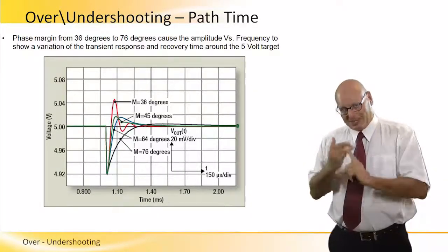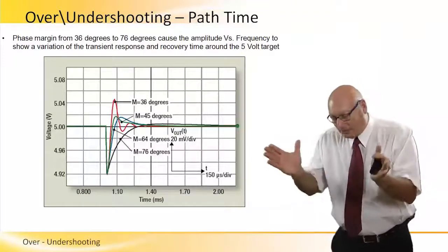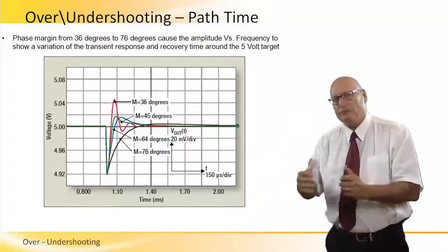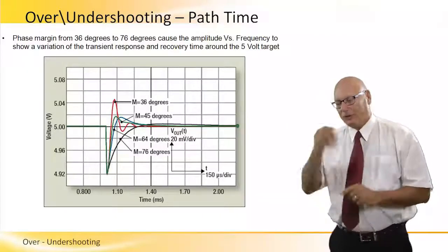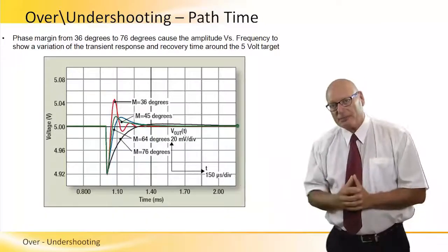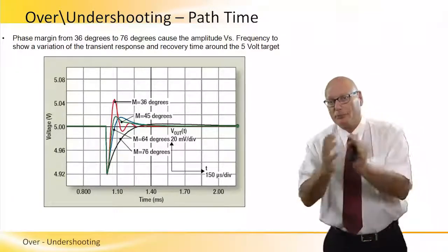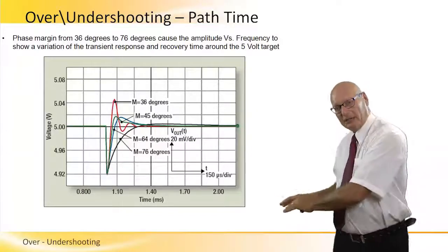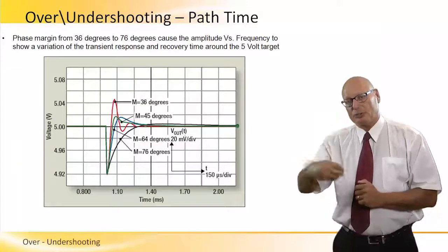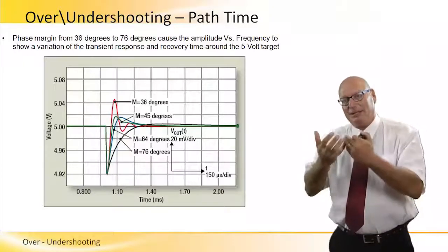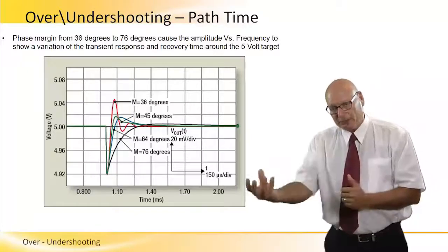First of all, we know the physical parameters and aspects of the task that we need to do. Once we know our robot and its technical specification, once we know the starting point and the ending point, and the time that allows us to go from A to B, we physically can calculate torque. And once we have the torque and the mechanical aspects of the robot, we can go fetch the Q value from tables. That Q value from tables, we apply it into the robot program, which we program offline in a computer. So that particular Q determines what kind of overshoot, undershoot characteristics we'll have. And it's basically a generation of the calculated torque and the calculated mechanics that we have for that particular task.